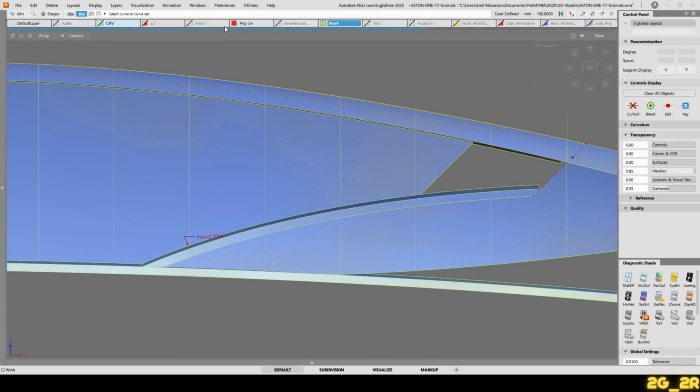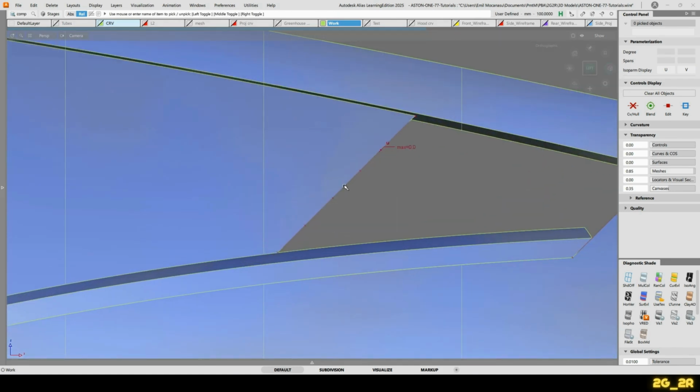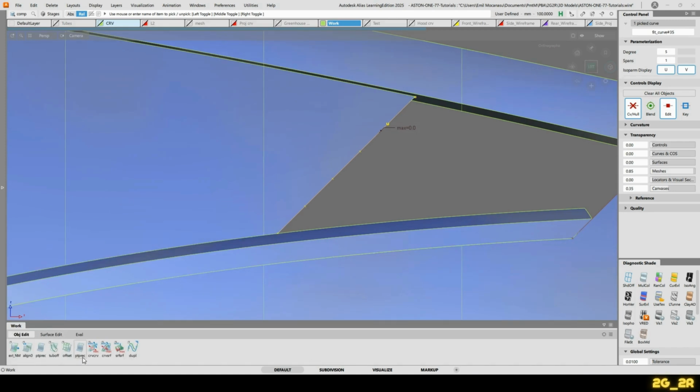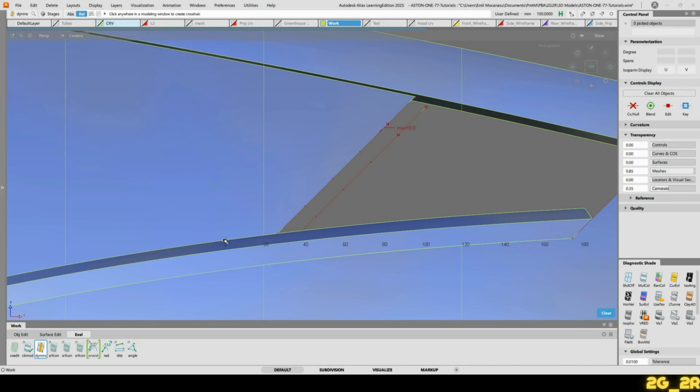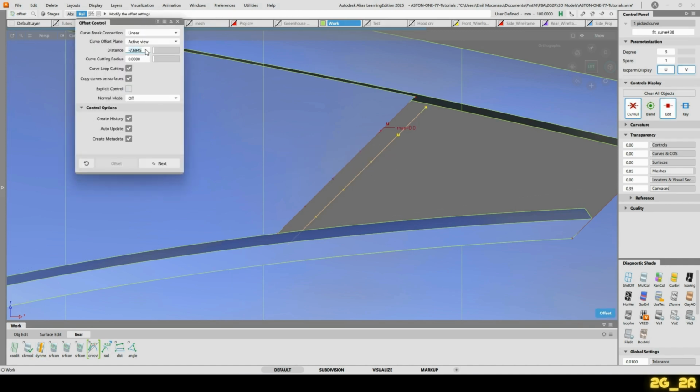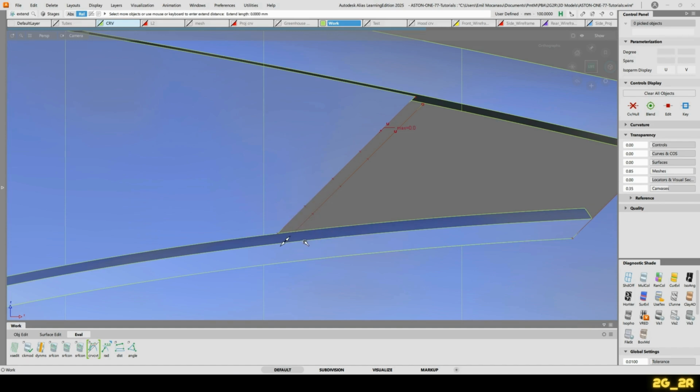Now I'm going to hide away the projection curves. Fit curve this one here. Extend it. First offset it, so it resembles this here. And let's do just a dynamic measurement because I'm eyeballing it here today. Got 5.2 in the side view. Let's go minus 5.5. That does it. I'll extend it till it hits that line there.